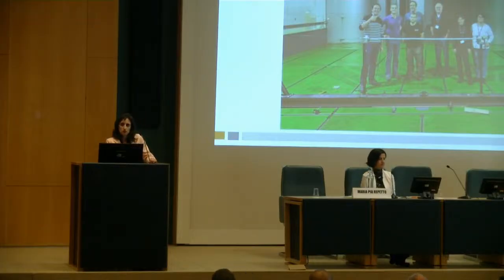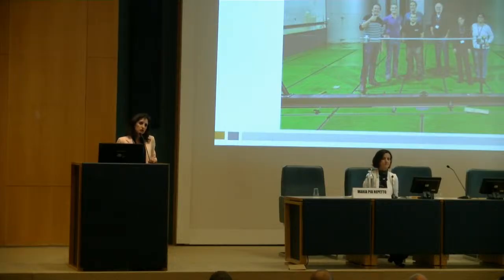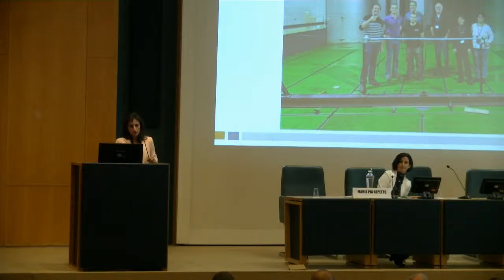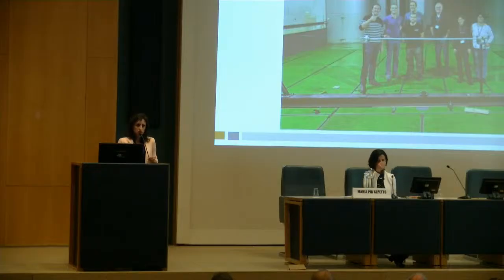No, we didn't measure the humidity. We measured the air temperature, and we measured the collected mass of ice through a known cross-section, which gave us information about the mass concentration of the snow in the approaching flow. And the density of the snow. This is what we measured.